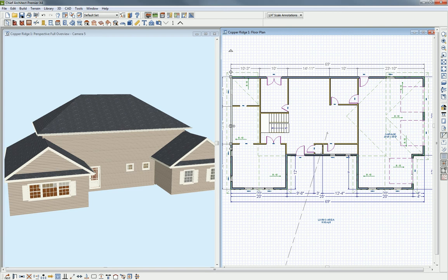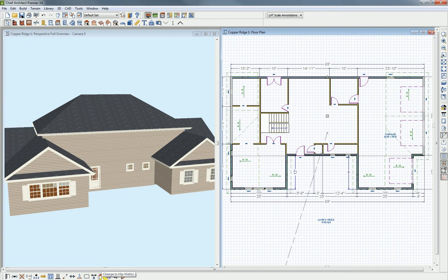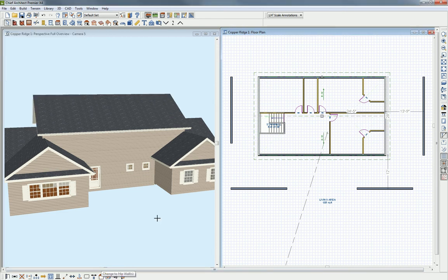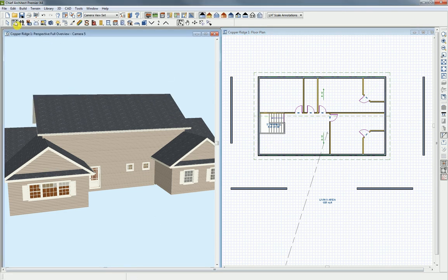So I'm going to hit Control and select this one. We'll change them to gables. Okay. And this one, I'm going to add a little bit more to it, but let's go up to our second floor. So I'd like to change these to gables as well. So I'll just Shift, select the two, click to gable, and let's rotate this around.